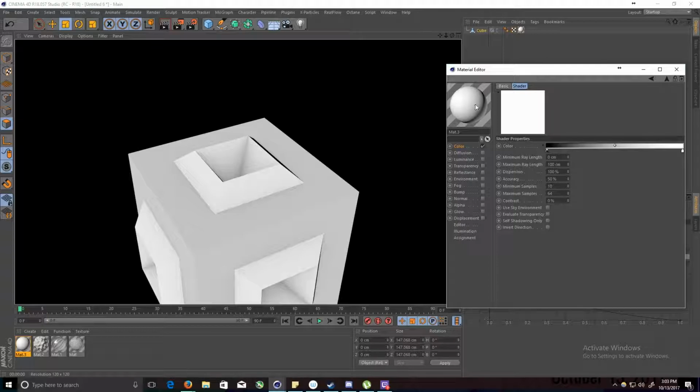So oftentimes what people do is use this filter, which when you export, when the render engine is dealing with that at the end, is just another black and white grayscale texture. You can use that to drive a luminance, which can fake subsurface scattering, which, if you render realistically, takes a hell of a long time because light is entering objects and bouncing around and leaving objects and going back in objects. So there are a lot of smart ways you can simulate effects a lot quicker than if you were to work realistically.